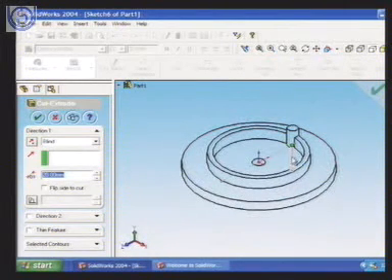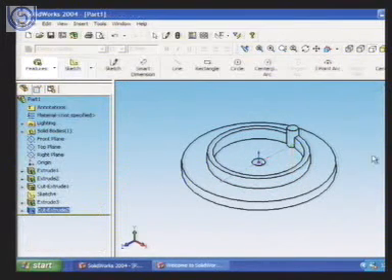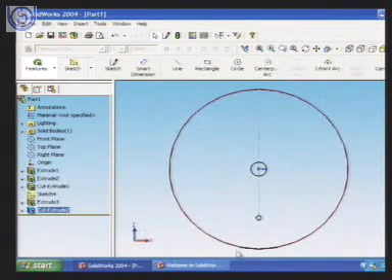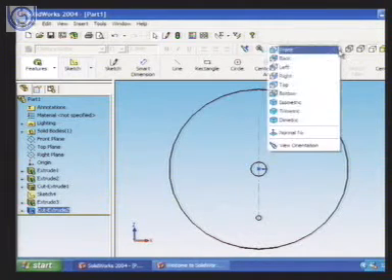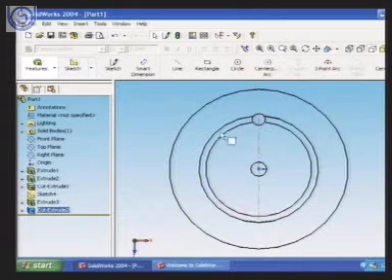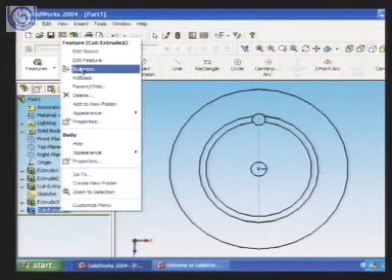You can see that it is in this direction, but if I give it in this direction, what will happen? You can't see it, because the sketch has been created on this surface. It has not been created on this surface. So when you see the bottom view, you will find this hole here. But we wanted to do it the other way round. We wanted to have the hole on this boss. So what do we have to do? We have to change the direction.